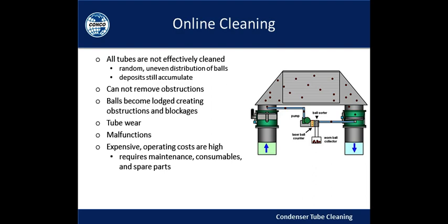Now, too aggressive passing of the balls, high frequency in ball passage, may also result in tube wear. Nonetheless, there are a lot of parts associated with this particular equipment that must be maintained. A crew must be trained appropriately, and the expenses and ball consumption can cost more than 2 mechanical cleanings per year. So, while these operating costs are high, if the condenser is large enough, the maintenance of the cleanliness during the operation period will be improved.